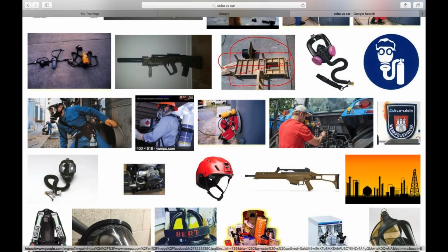And then also SCBA offers the best protection, like we just talked about. Conditions that require an SCBA. Now, these conditions require it, right? Leaking cylinders or containers, smoke from chemical fires, chemical spills that indicate a high potential for exposure to toxic substances, atmospheres with unknown contaminants or unknown contaminant concentrations, confined spaces that might contain toxic substances, or oxygen deficient atmospheres.